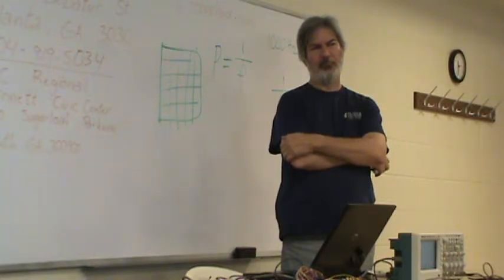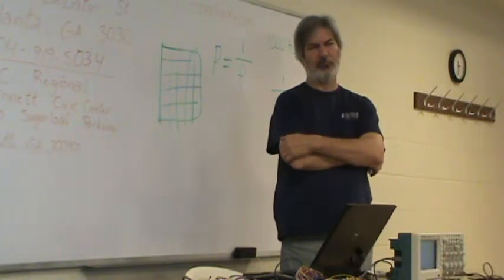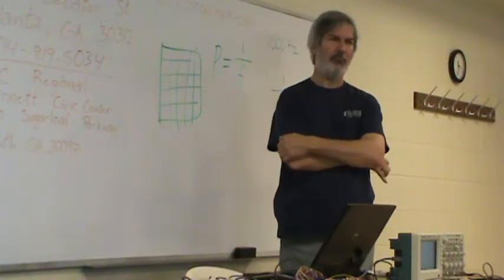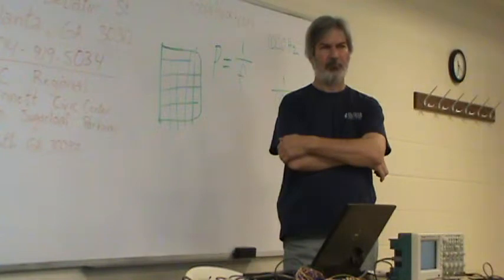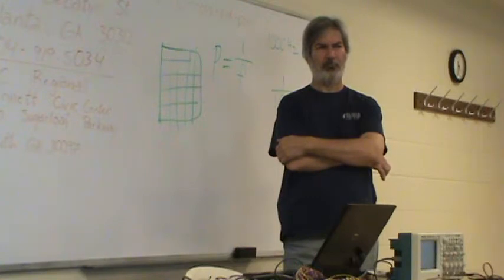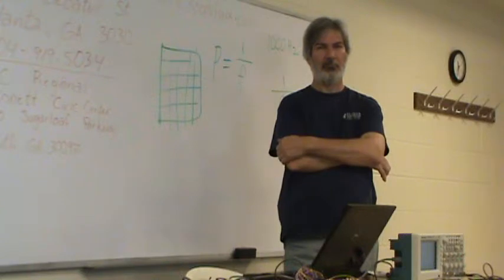If you set the trigger coupling to AC, it'll ignore that DC offset. Doesn't matter what the DC offset is, it'll trigger on that 1 volt. It's just like a capacitor in series with the signal and the trigger, whereas DC, it's DC coupled from the signal to the trigger. Okay. Got it. Those are my questions.